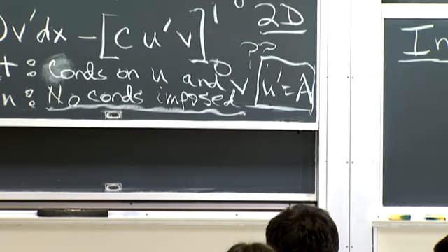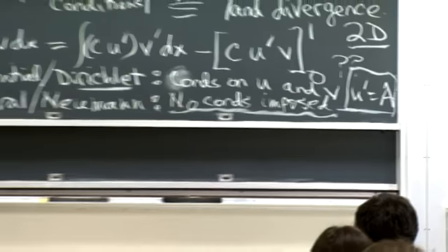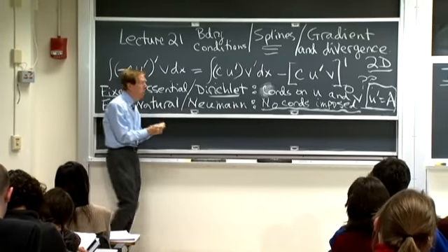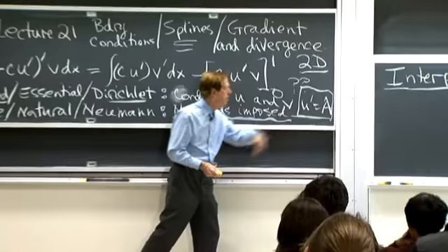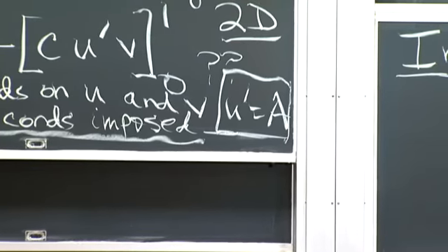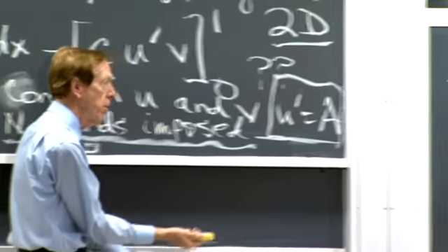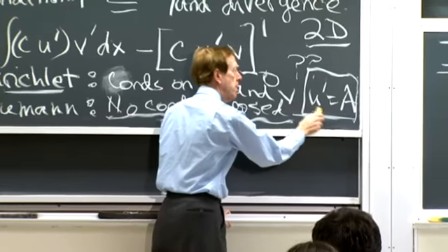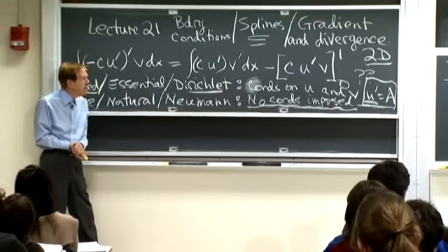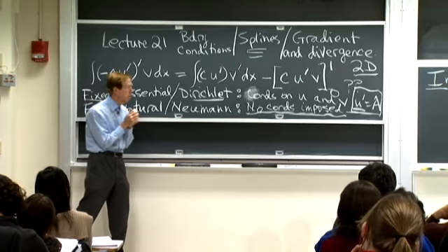How does the weak form and the Galerkin approach deal with a non-zero natural condition, a non-zero Neumann condition? That would be the right words. So this would be, in a second order problem, a Neumann condition, and I'm thinking, what do you do if a isn't 0? Somehow that has to show up in your finite element equations, right?